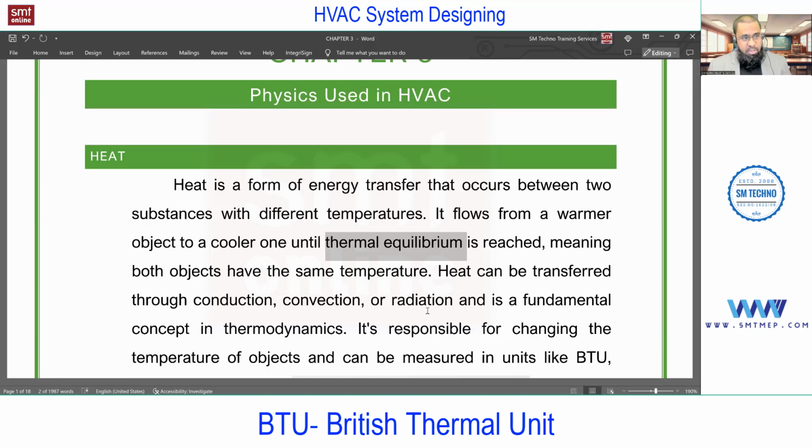This term will also be used at the time of load calculation, especially when learning heat gain through partition, floor and ceiling, because heat gain through a partition means between two rooms. If the two rooms are at the same temperature, there will be no heat transfer. I'm just trying to relate these terms with the load calculation so that it will be helpful for us later.